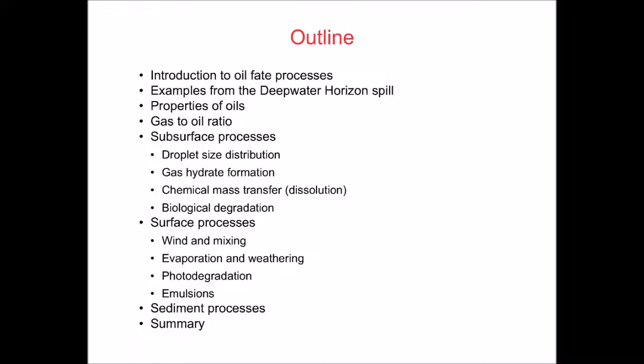So we'll start with an introduction to the properties of oil that are involved in calculations of oil phase, discuss the gas-to-oil ratio, and then we'll look at a series of processes, first in the subsurface as we form droplets. In the deep water, perhaps a gas hydrate could form on the bubbles and droplets. We'll have chemical mass transfer, which is dissolution, and biological fate, which is biodegradation.